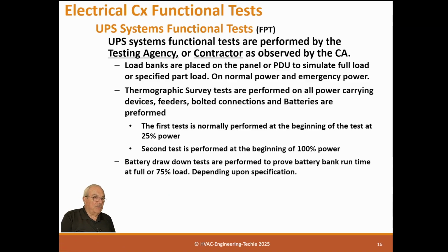And what we're doing there is we just trip the main power going to the system. And since we've got a load bank on the devices, we run it until the batteries get to minimum shutdown. And we watch the UPS shut down when the batteries are low. And we're also doing thermographic on the batteries at the same time to see how they're performing during this whole drawdown. Now, when we do that, we can recalculate how much battery time the system has at full load. And it's important to know that the system will last 30 minutes, 20 minutes, 10 minutes, 5 minutes, whatever it's designed for, and the battery drawdown is done to do that.